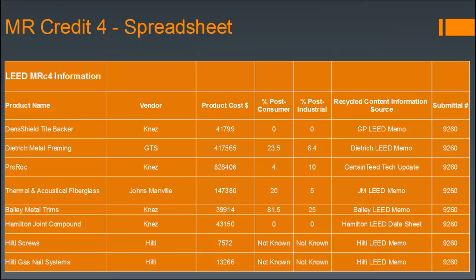We feel strongly in our LEED consulting that there needs to be more integration of LEED with construction management protocols. As I mentioned before, it should be in your safety meetings. The quality assurance person should be watching what's coming on site in terms of low emitting materials, FSC certified wood, and other things we'll look at at later points in the webinar. The main thing is to track everything coming on site and make sure that everything's clearly specified in your specs and that it's carried throughout your construction documents and execution on site.